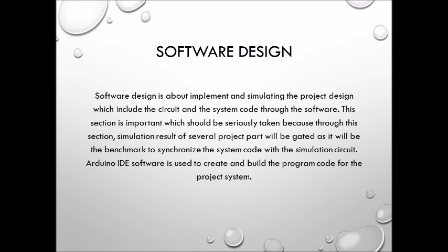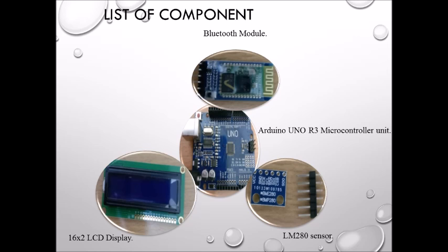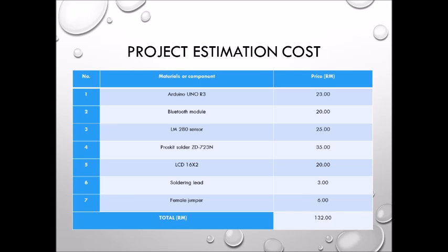For the result, I have already done the programming for the BMP280 with LCD display and wiring. For the define line, for the first line, we define the address as 0x37.